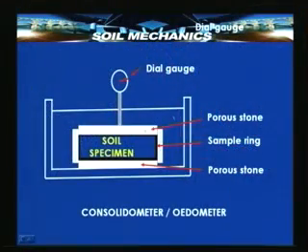So, the water can go downwards like this, it can go upwards like this, and the expulsion of water in both these directions will lead to a compression of the soil essentially in one dimension, and this is by and large an experiment which enables us to do, at the laboratory level, a one dimensional consolidation of a soil.